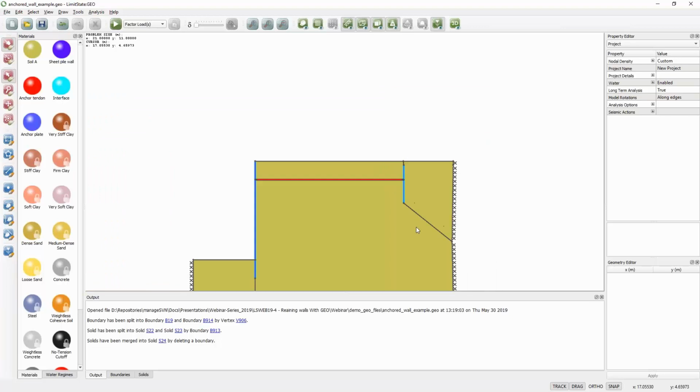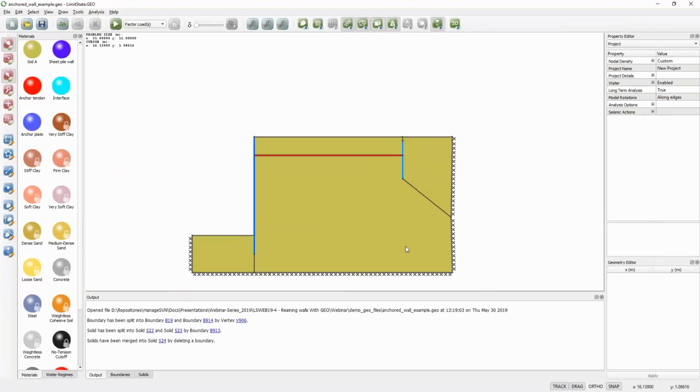It's simply that we just cannot have effectively lines floating with free ends in the problem, and it's just necessary to put those lines in. It shouldn't really affect the analysis in any great detail. It will slightly affect the distribution of nodes. If I do this analysis preview nodes, it shows me where all the nodes are going to go. So it's slightly different offset of nodes in this area than in here, and there's also nodes along these boundary lines. But generally, if you take the default settings in the software, it doesn't make a significant difference to the